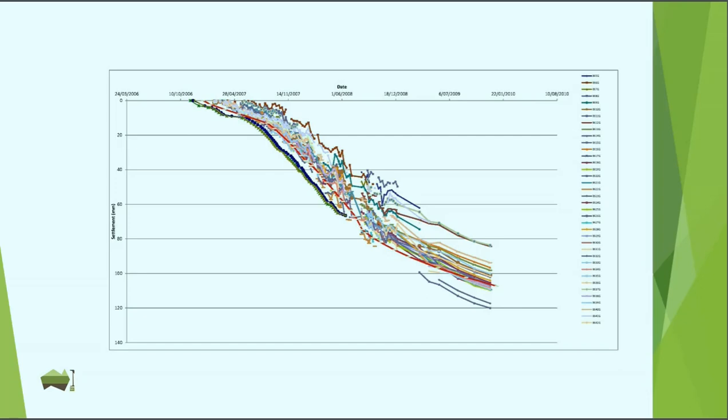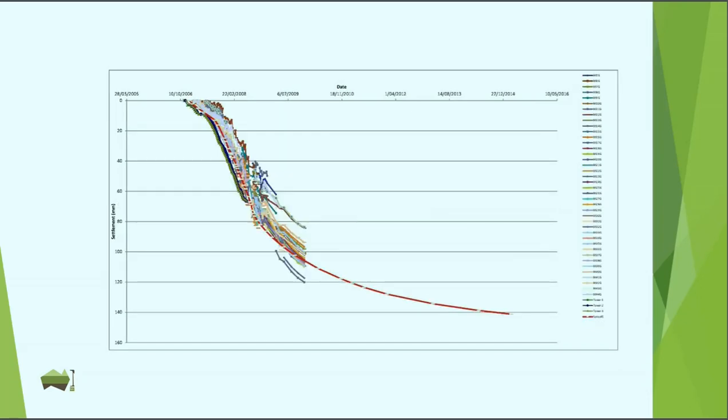I felt quite happy with that, and therefore I made an extrapolation of how much more settlement there would be due to consolidation of these deep clay layers, and that was out to the end of, or sometime in 2014.